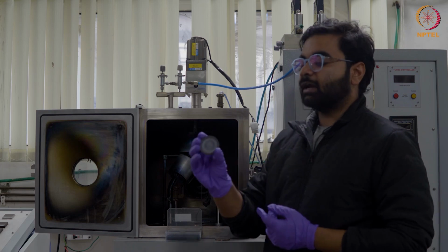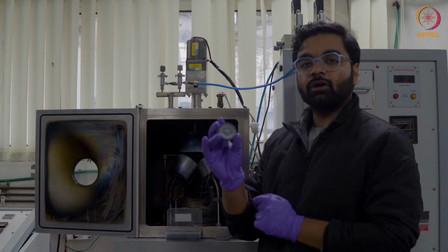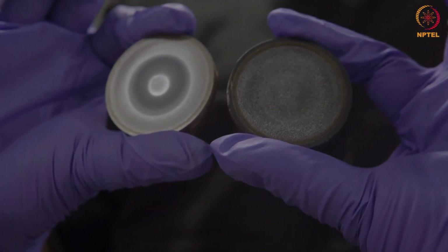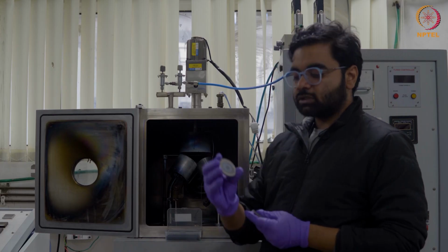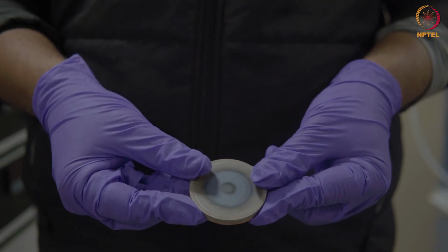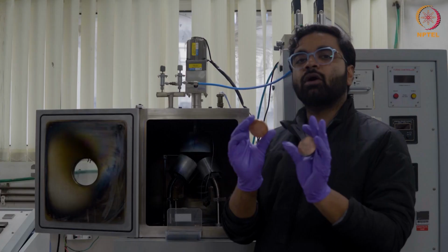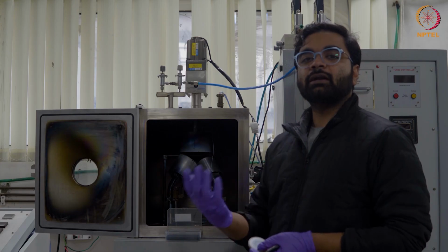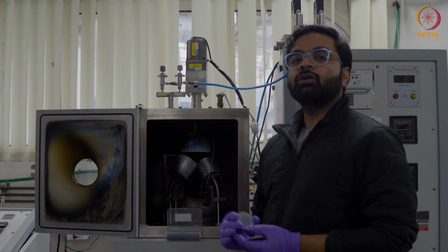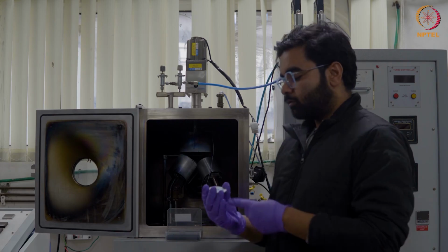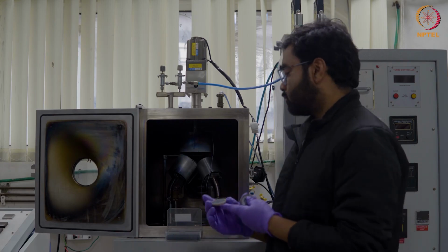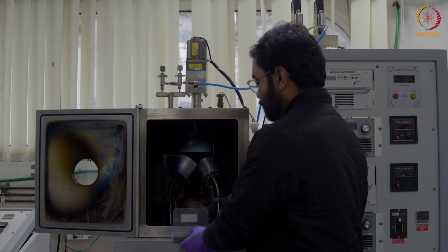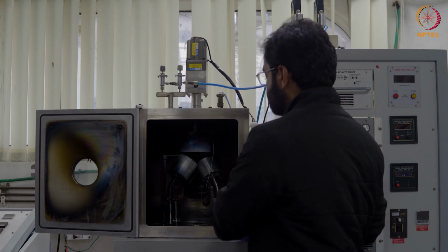Okay, so this is a target material. What I have in my hand is a silicon carbide target. Different material targets are commercially available in the market, so that you can use. In this case, what you see is the TiO2 target. TiO2, titanium oxide target, with a copper backing. Both of them will have a copper backing. The copper backing plate is given because normally oxides don't have that conductivity, so it becomes a challenge. In order to take care of that conductivity issue, we do a backing of the copper plate. The copper plate allows the sufficient conductivity that we require. Okay, so this is the target that we require in this case.